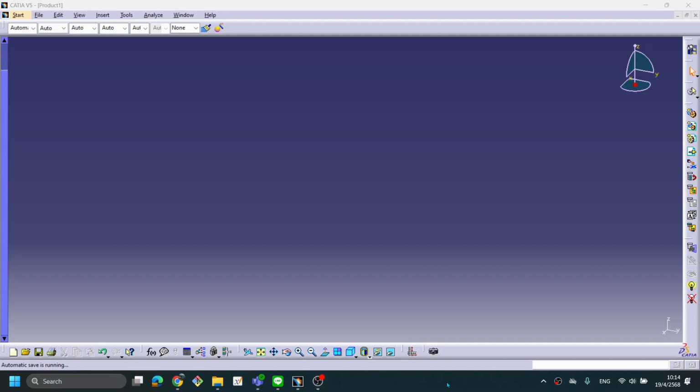The SUM module is the CAM, computer aided manufacturing, module in CATIA, called the surface machining module. Right? It generates the G code and lets you define the two parts, and use the cutting tool to remove the material, going along with the part style you generate by yourself, right? But I propose some techniques, because of the specific mini CNC we have, right?